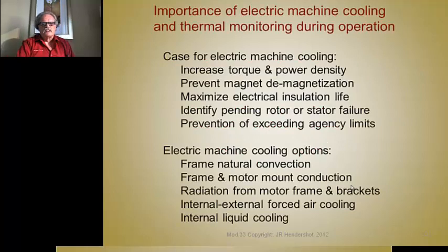The importance of thermal analysis of electric machines can't be overemphasized, and the modeling or monitoring of the temperature condition while it's operating. If you take control of the cooling of the machine, you can increase the torque and power density.